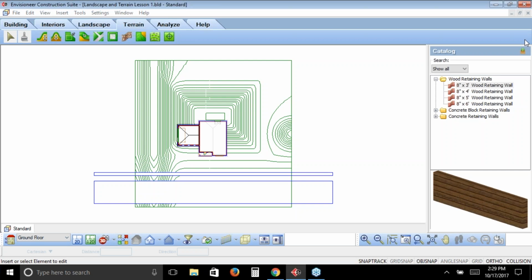It wipes away any adjustments that you had made previously and returns it back to a flat terrain. So you can't use them in conjunction with each other. You either use the first 4 tools or you use the spot level point tool, and then you create that slope by the spot points that you put in.